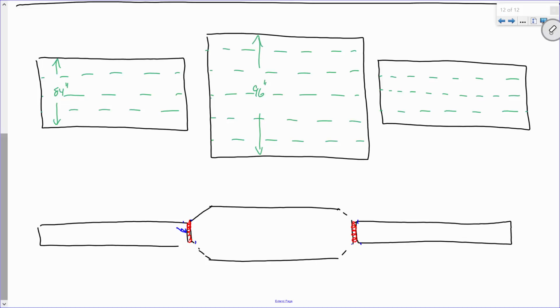I had a question earlier about cross frame spacing. How far apart do you want to space your cross frames? A better way of looking at it would be, instead of looking at how far apart to space your cross frames, the best way to look at it is, how can I eliminate as many cross frames as possible? I would say on average, cross frame spacings tend to go around 20 to 30 feet. There used to be this rule in the spec that your cross frame spacing couldn't go above 25. It's not in there anymore, but it's funny how everybody kind of still uses that. And cross frame spacings don't really tend to get that much larger than that anyways.